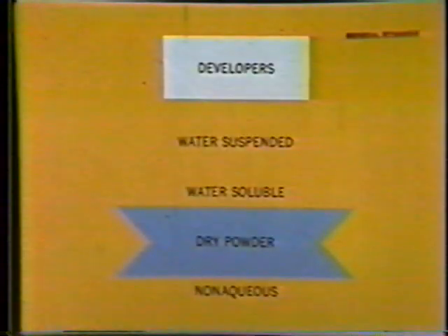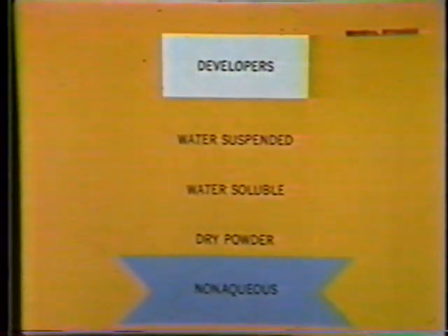Dry developers are more adaptable to rough surfaces and automatic processing. They're also the easiest to remove. Non-aqueous wet developers are used mostly for in-field testing and spot checks, and when greatest sensitivity is required. Controlling specifications and standards decide material and equipment requirements. They also establish required sensitivity.